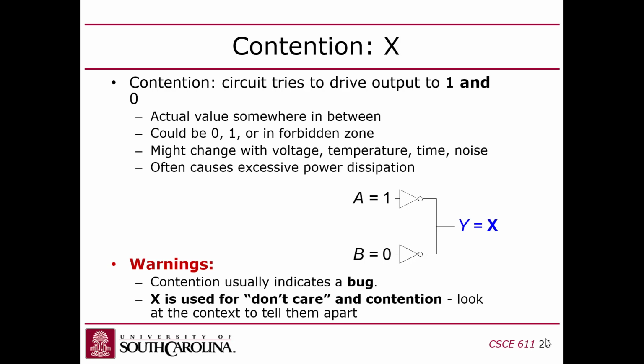However, when you're simulating your code and you see an X, that doesn't mean don't care. That means that's bad. That means there's a problem. Generally, what it means is there's contention.